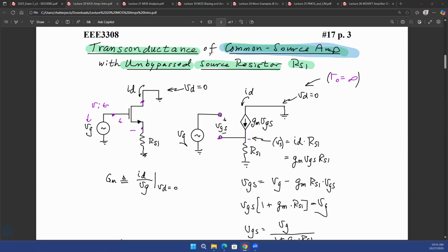Okay, all right. What we had been looking into in the last lecture was this type of amplifier where you had a MOSFET, with the source connected to a resistance. You already know that this is called an amplifier with source degeneration. Now, what type of amplifier is this? Since you're applying your input at the gate and you're looking at your output at the drain, the common terminal would be the source terminal, right? So you have these three terminals: source, gate, and drain. Let's write them down.